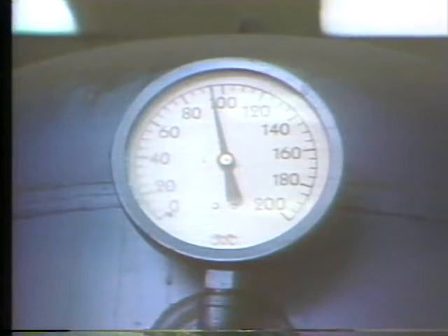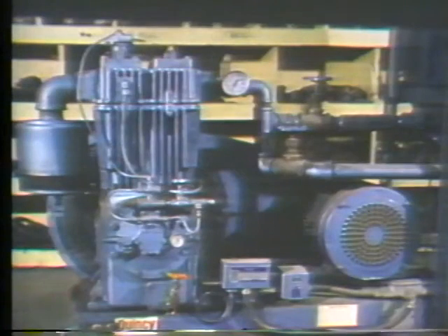What this means in fluid power systems is that hydraulic reservoirs tend to be much larger than pneumatic receivers. Since liquids aren't compressible, a reservoir must be large enough to store all the liquid in the system. Air, on the other hand, is compressible, so it can be stored under pressure in a relatively small receiver. It's this stored pressure that enables the air in a pneumatic system to do work. As air is used and the amount of pressure in the receiver is reduced, the system's compressor starts up and recharges the receiver.